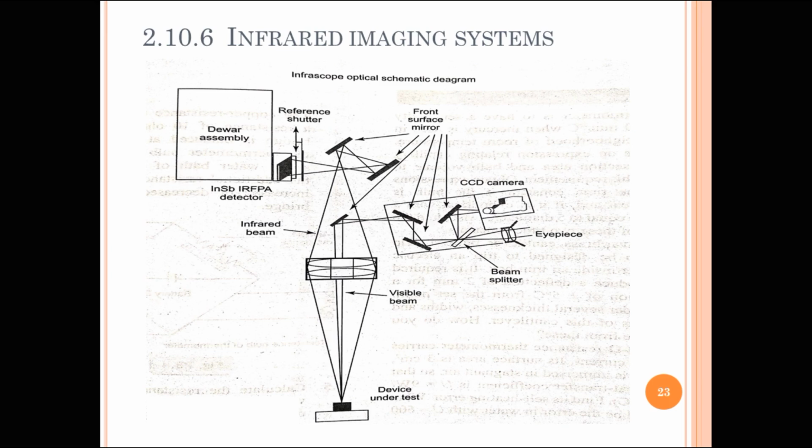The scanner gives the temperature profile across the moving web of film during its manufacture, allowing better control of the process. The temperature profile of the cement kiln reveals local hotspots which indicate a need for repair of its refractory lining. For that purpose, both steering and scanning systems are available, but steering systems are preferred in many cases since they do away with the complex moving parts and can often gather more of the available radiation.